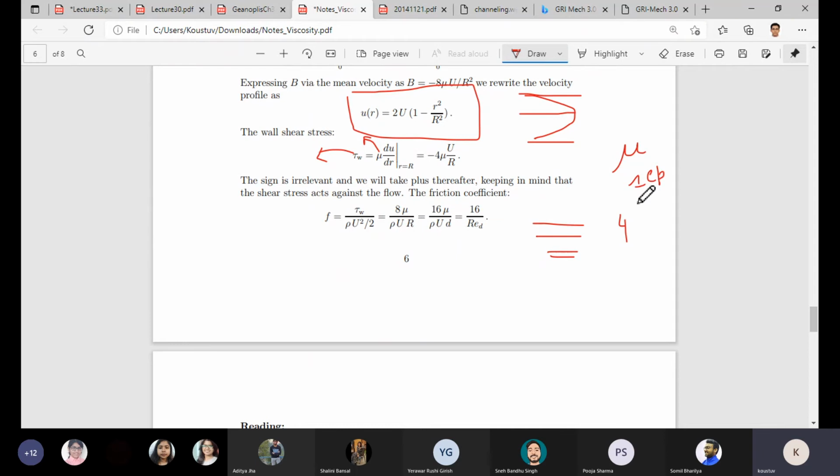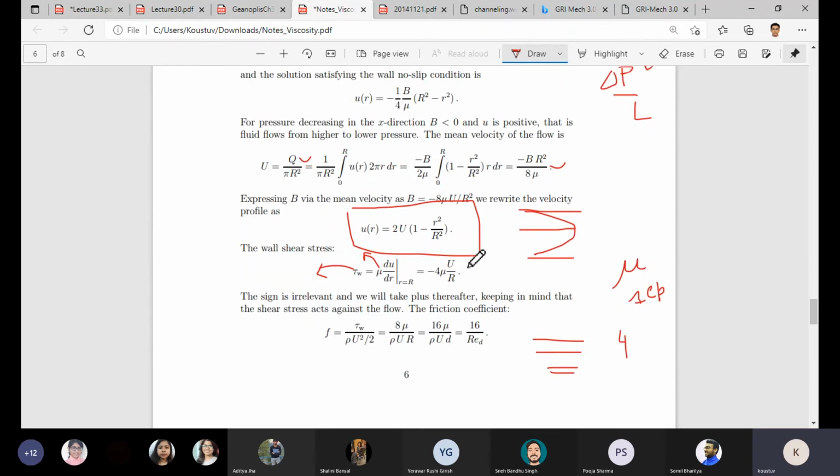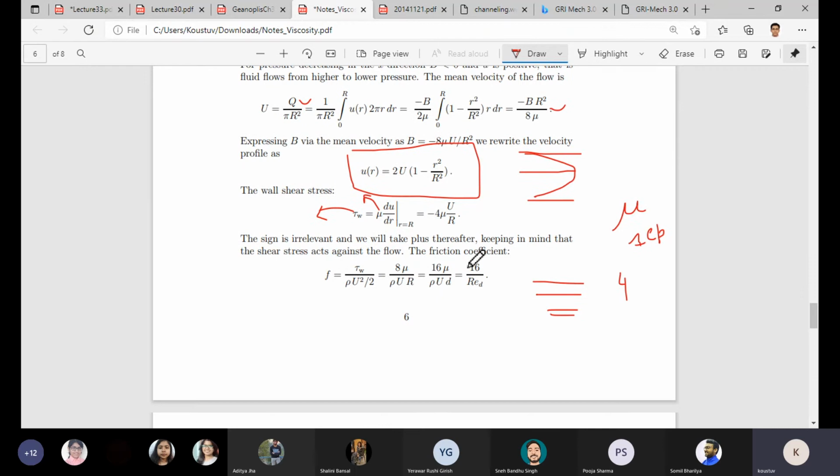So how much off from the original or the actual one. If you take Asphalt Viscometer, you will more or less get 1 cp. But here in this experiment, though it says pipeline viscometer, it's actually not a viscometer. It is basically just a straight portion of the pipe or tube. We have varied the diameter, varied the length, and just taken that to calculate delta p and other measurables like q.